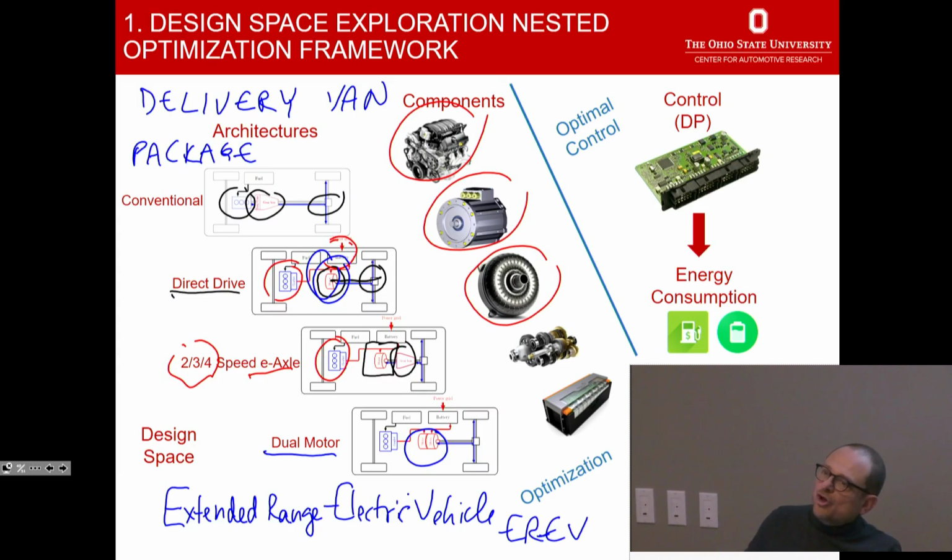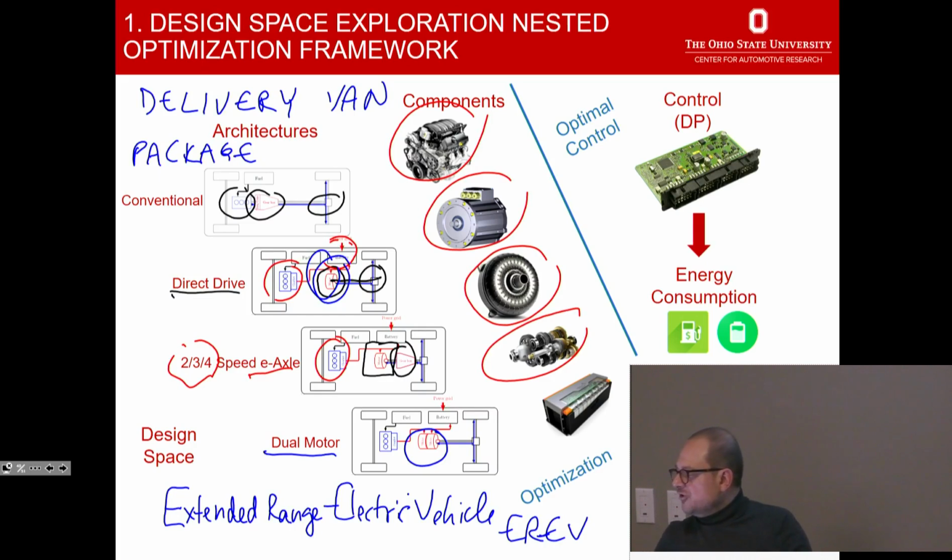So for example, do you need a torque converter in the transmission? Maybe, maybe not. Okay? Is your transmission a stepped automatic transmission, or maybe that uses clutches and the like, so planetary gears, or could it be a lay shaft transmission with 2 or 3 speeds, kind of like a manual transmission, maybe automated? So that's the option of the transmission. That's a lay shaft transmission here. And of course, you have a trade-off, right?